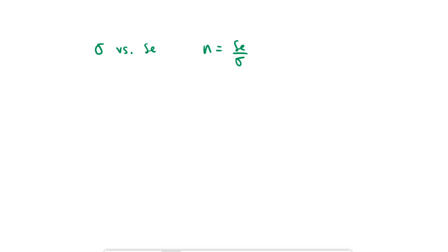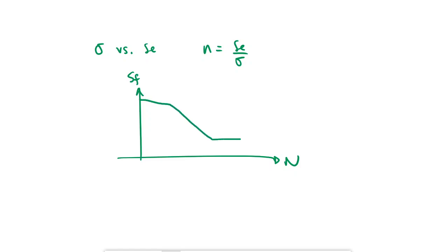Again, just an alternating, completely reversible stress. And your S-N diagram, so S_F, actually fatigue strength versus the number of cycles, you have something that looks like this. And this is 1,000,000 cycles, this is 1,000 cycles. You start with S_UT, and then as the number of cycles increases, you have a fraction of your S_UT here, and then from 1,000 to 1,000,000, this is described by a straight line.